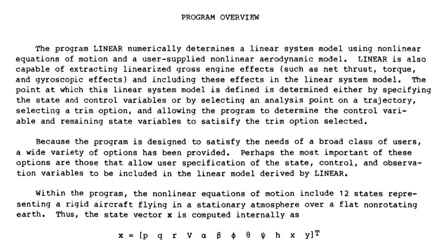On page 16, they specify that, within the program, the nonlinear equations of motion include 12 states representing a rigid aircraft flying in a stationary atmosphere over a flat, non-rotating Earth. So here, it's not just a flat, non-rotating Earth, but the atmosphere is stationary as well.